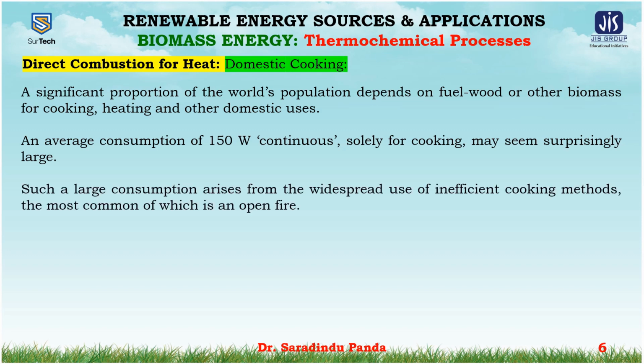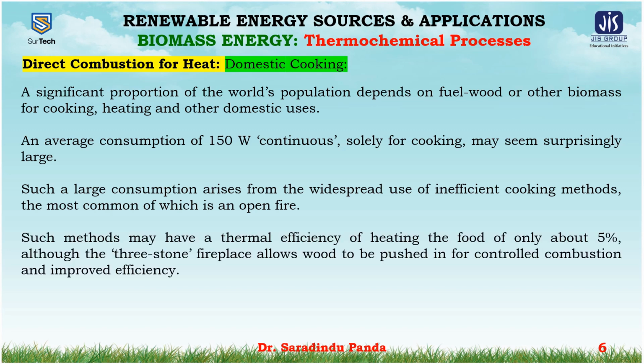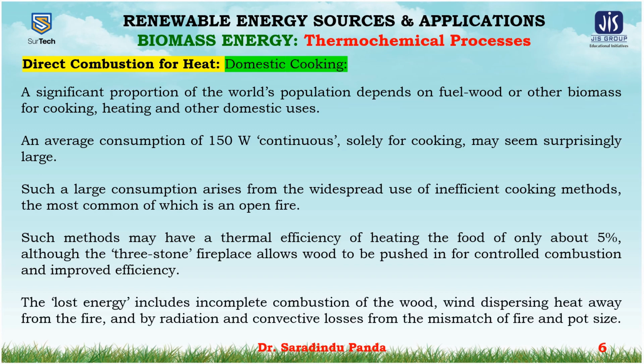Such a large consumption arises from the widespread use of inefficient cooking methods, the most common of which is an open fire. Such methods may have a thermal efficiency of heating the food of only about 5%, although the three-stone fireplace allows wood to be pushed in for controlled combustion and improved efficiency. The lost energy includes the incomplete combustion of the wood, wind dispersing heat away from the fire, and radiation and convective losses from the mismatch of fire and pot size.